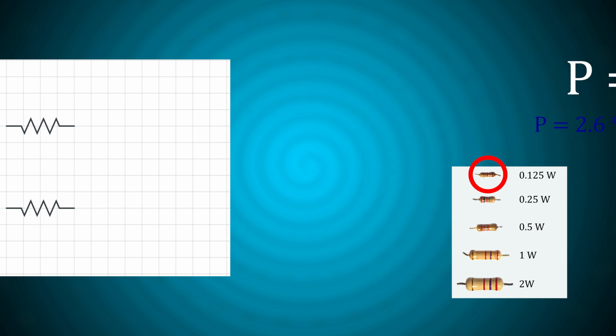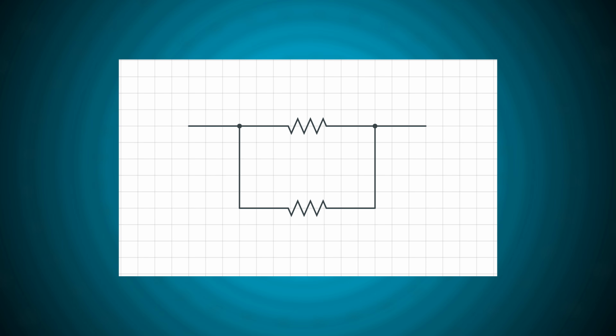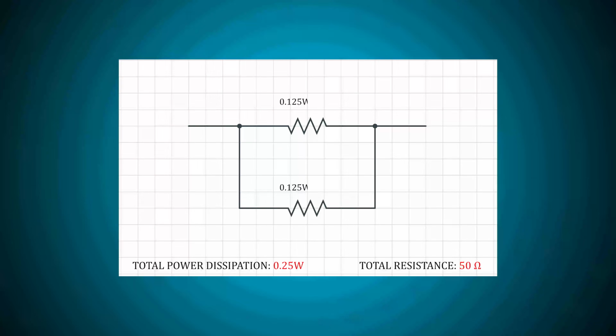Take two resistors and connect them in parallel. This will, first, lower resistance in half. Second, double the power rating. So, in our case, to come up with a 0.25 watts 50 ohms part, we need to use two 100 ohm 0.125 resistors.